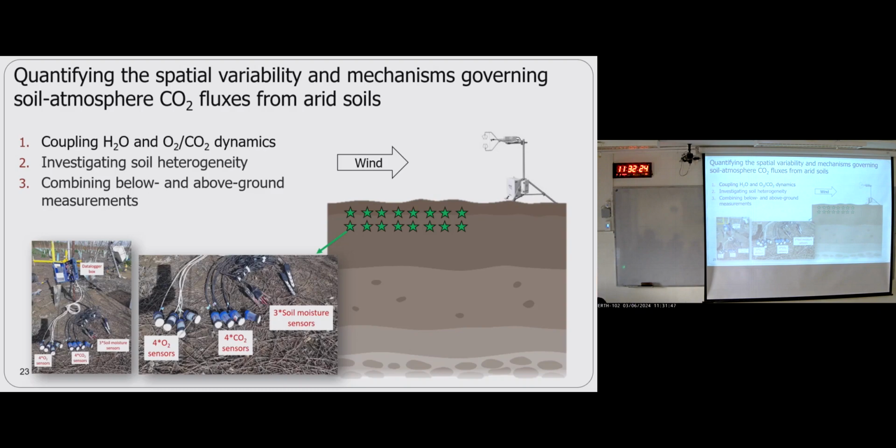So we developed a very simple, stupid device: a 50 mL Falcon tube that we cut, and we add a white membrane, a hydrophobic membrane. This is without the sensor, but we solder the sensor inside, put it inside the enclosure, and now I can put it in the soil. Under rain events or irrigation, we don't care. Gas still gets inside the chamber because the membrane allows gas to go in, but not water. And the electronics can sustain the water and the irrigation.